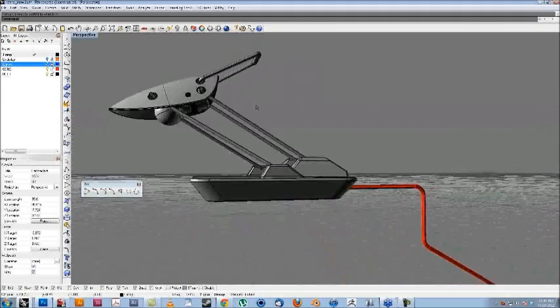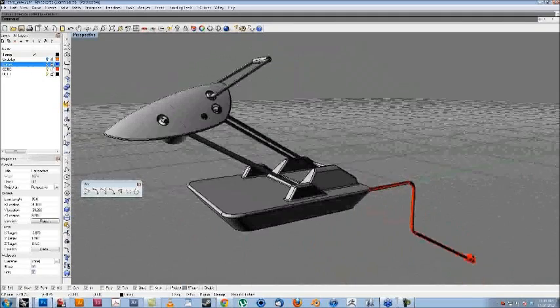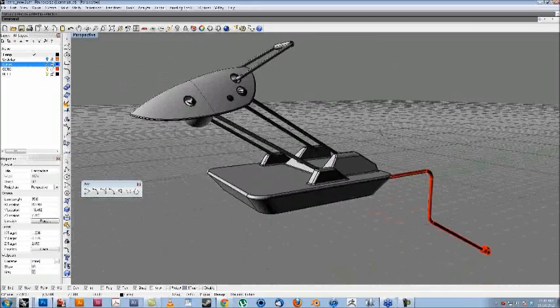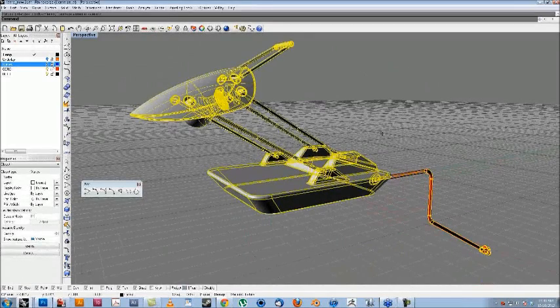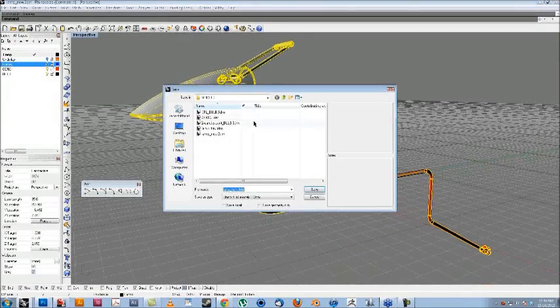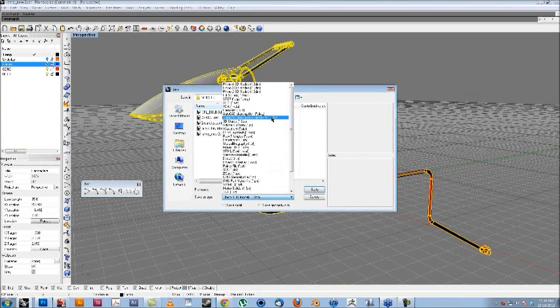So we're going to call this done at this point, just to keep things moving, and select everything and hit Alt FA. What that'll do is give you the option to save this out as a different file. Now, Rhino has a whole bunch of different saving options. For the people who use SolidWorks, we've got IGES and step file in here.